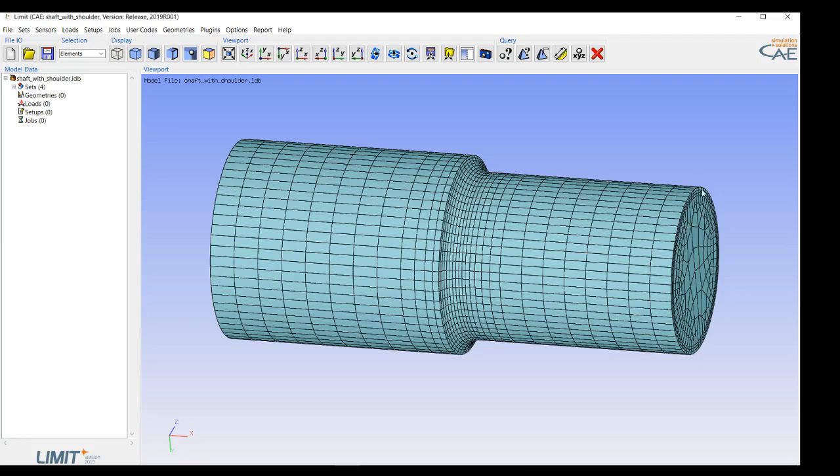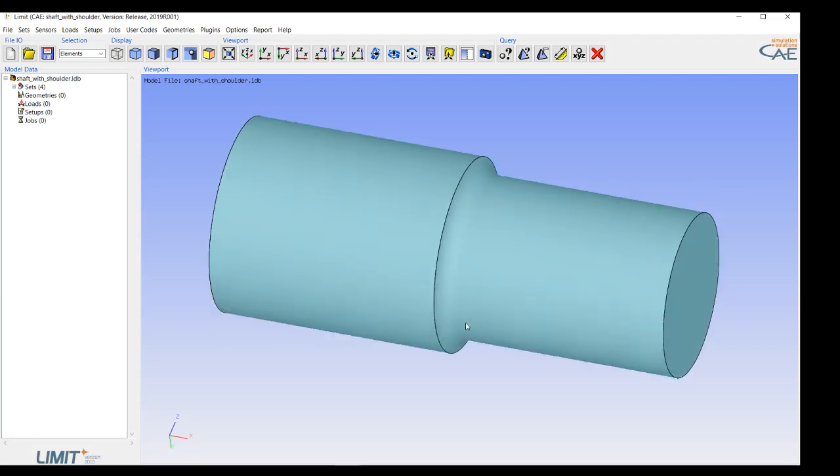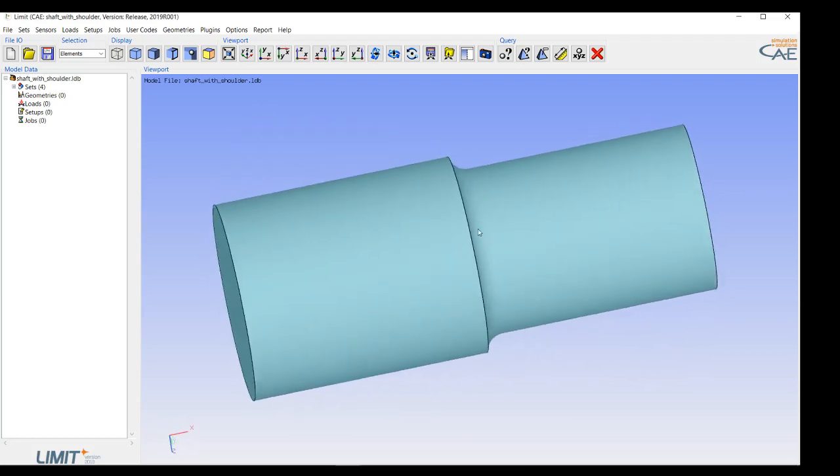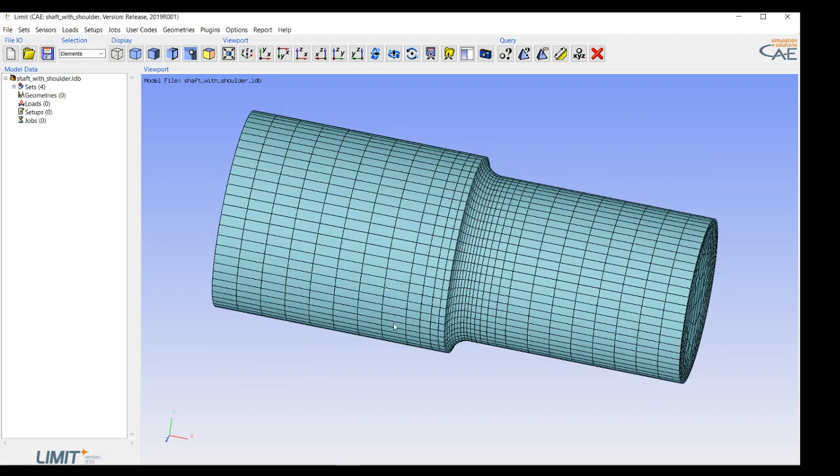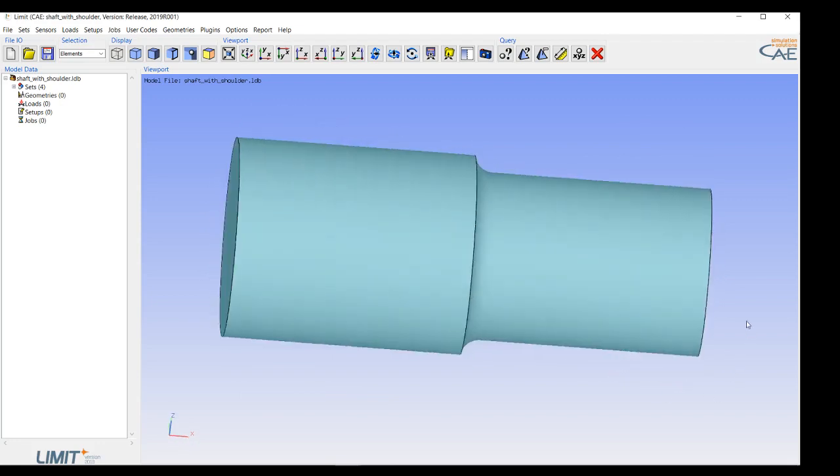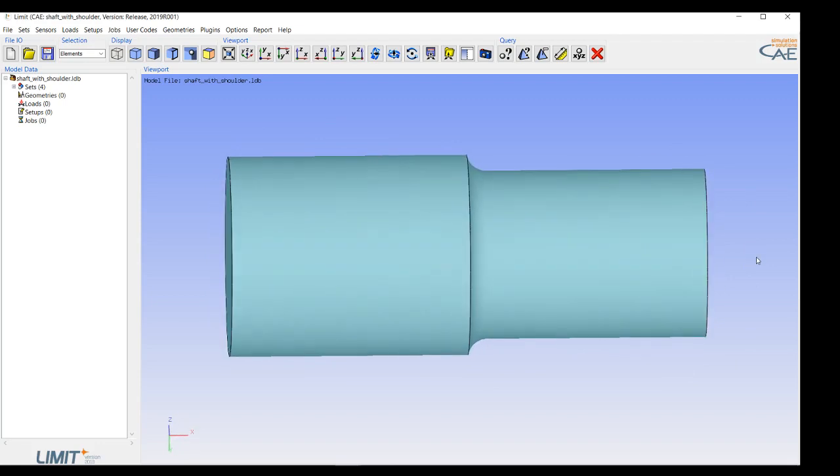And due to the load importing numerical fluctuations, the node with the highest stress is somewhere here where I introduced the torsional and bending loading, and I'm not interested in results here in this plane. I'm more interested in results here in this area. Okay, so in the first step we have defined the area which we want to assess, and